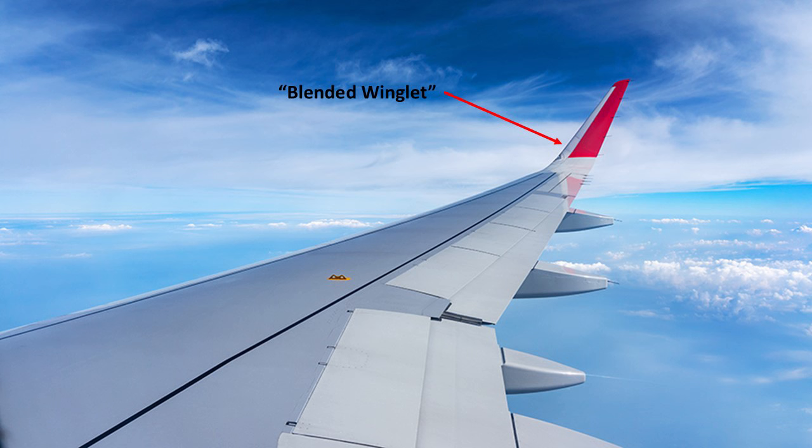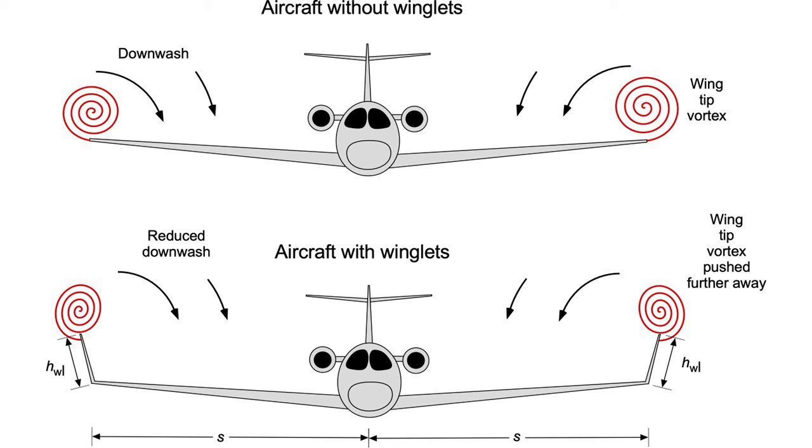One of the earliest solutions to decrease induced drag, besides increasing the aspect ratio of the wing, that is, was what's called a winglet. What winglets do is alter the span-wise distribution of circulation along the span of the wing, and naturally this alters the structure of the trailing vortex system downstream. The induced drag reduction due to the addition of a winglet is a relatively trivial calculation, and it's easily verified with vortex lattice analysis. However, it's easier for some to consider the flow field itself rather than just the numbers, in which the winglet is inserted when added to an existing wing.